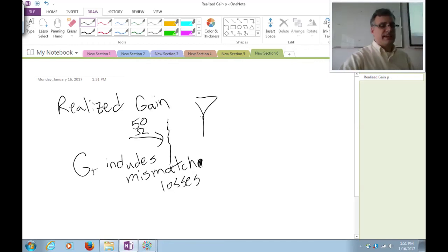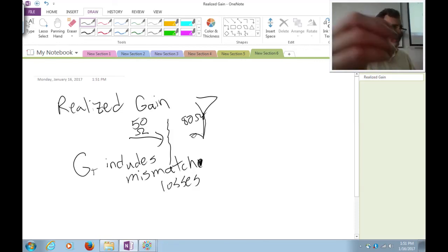So for example, if this antenna is only slightly matched to 50 ohms, maybe the actual impedance is 80 ohms. They tried the best they could to match it, but it's got a little bit of residual reflection at the frequency that they want you to operate it at.